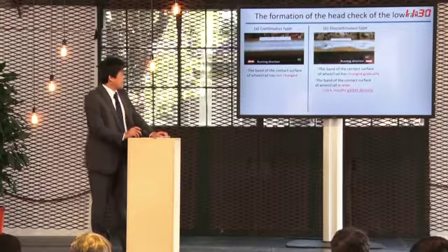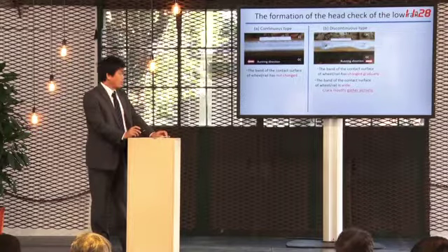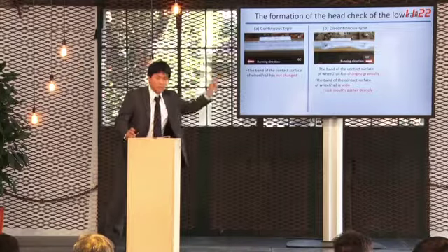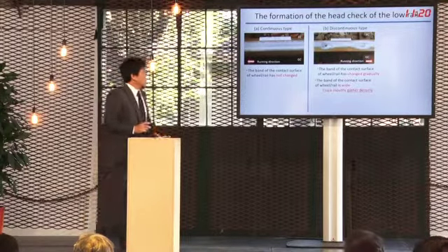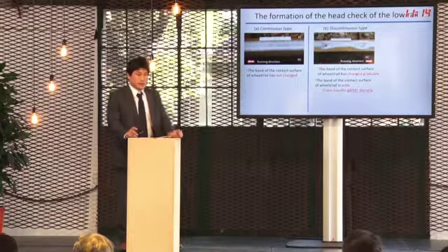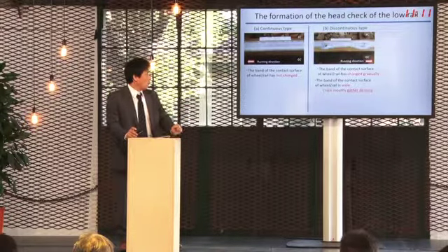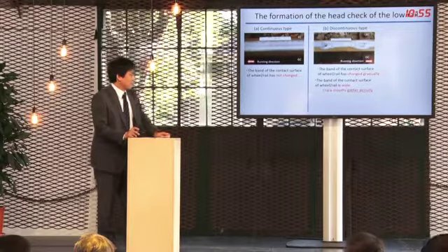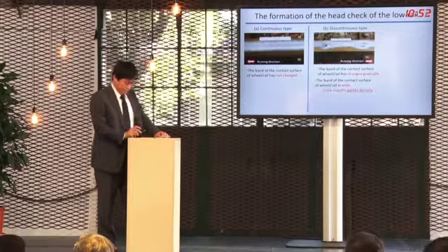From the on-site investigation, head check was classified into 2 types. That is, continuous type and discontinuous type. About continuous type, the band of the contact surface of wheel and rail is not changed. On the other hand, as for the discontinuous type, the band of the contact surface has changed complexly. Especially, the contact band is wide. Where the contact band is wide, crack mouths gather densely.